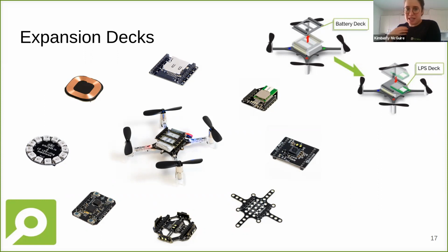During my own research, I actually added a camera on top, and there was also one of the multi-ranger decks with the ranger sensors. And that was already on the border. If I turned the camera off on the Crazyflie, it was able to fly fine. When it was on, it wasn't. So power is definitely also a big factor here. An average expansion deck weighs about 1 or 2 grams, I would say. Except for the QI deck, the one here, that one is a big one.